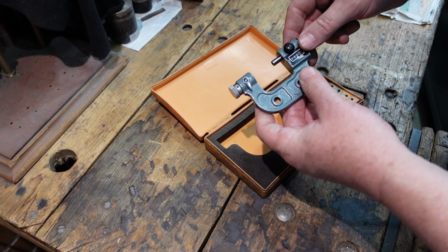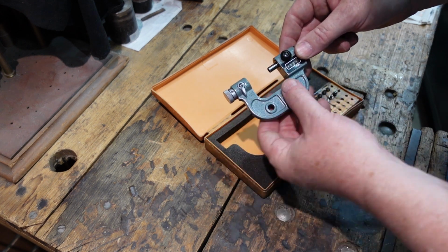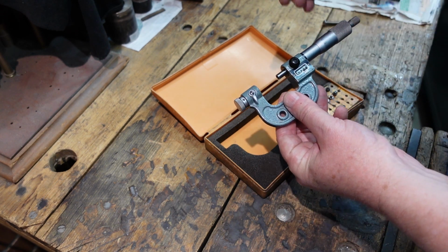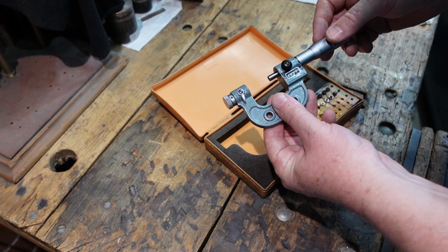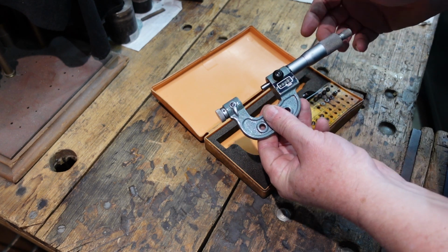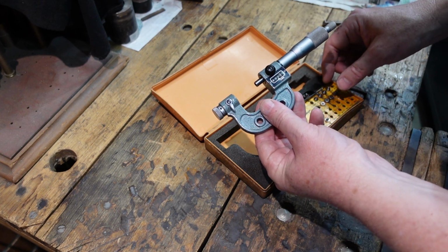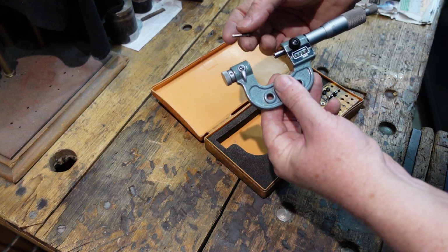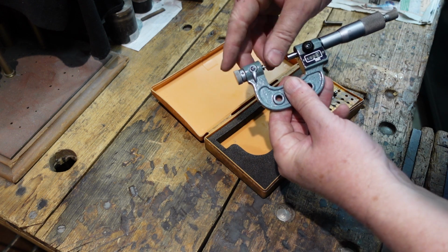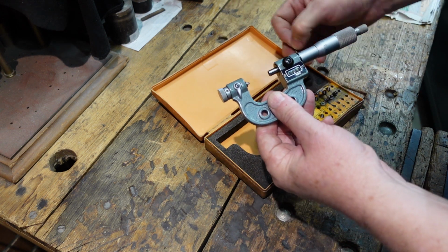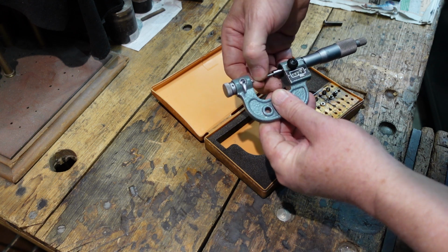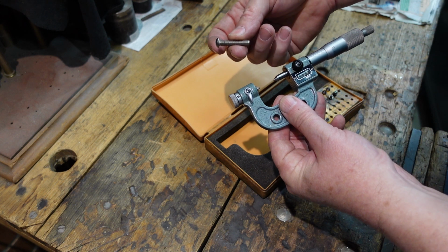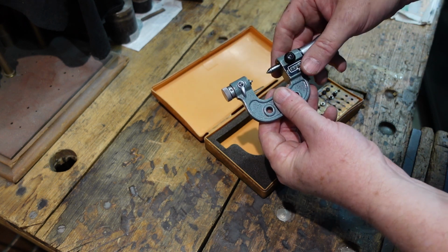This is a Mitutoyo. It's in rather bad shape. I need to make up some cheek pieces for it and clean up the case, possibly even make up a new case. But because of a question, I thought I'd just run through how it's used, what it does. So this particular type has got removable anvils, and they just pop in there like that, and the anvils are sized for the pitch of the thread that you're looking at. So you need to get your thread pitch gauges out and check what your pitch is so you can work out what it is.